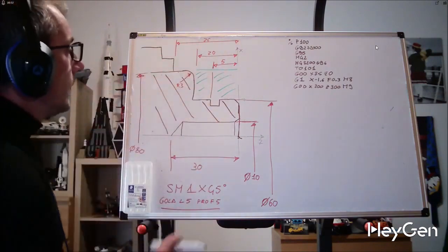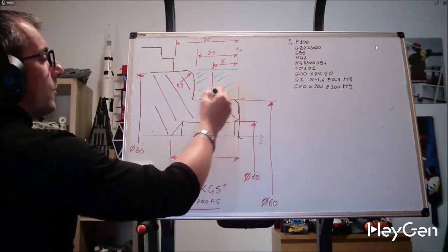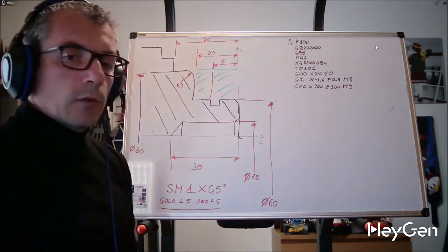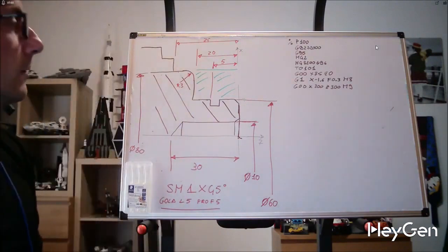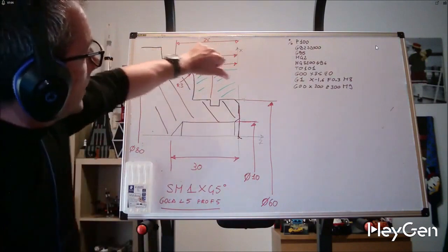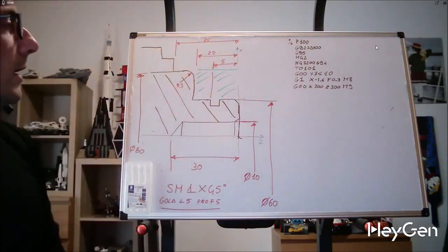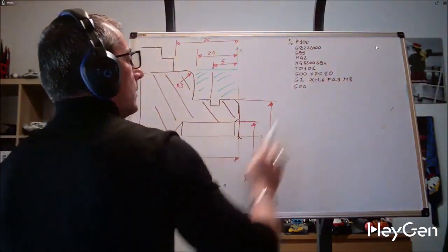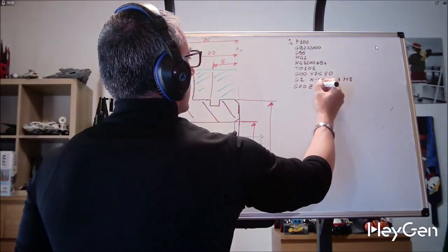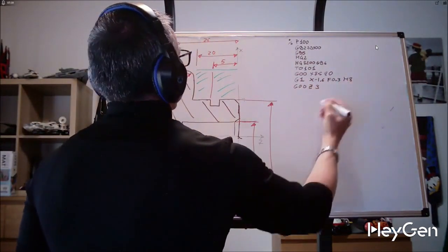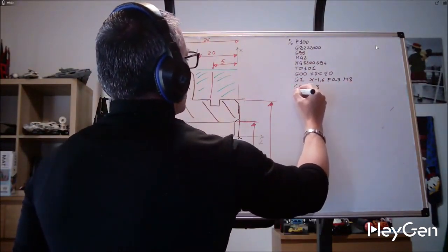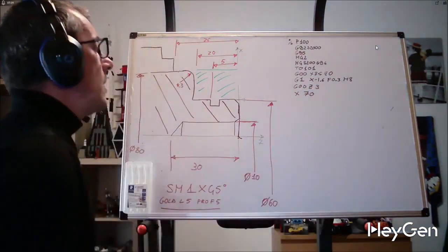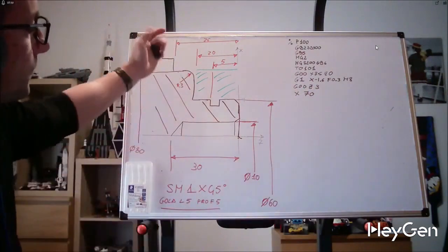Now, we know how to make the profile from point 0 and follow it all the way. This is because our concern is to move in space. Now with the same tool, if I want, I can go and remove all that excess material. So, instead of moving away completely, G0, Z3, I leave the water on. And then, still in G0, so I won't repeat it, X70. Let's say we have a nice sturdy insert, and we can easily remove 10mm at a time.